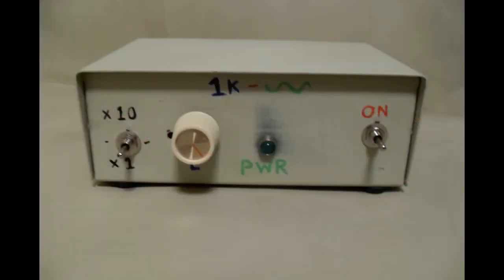Optionally, on mine, I added an LED. I have a volume pot. I put in a switch to toggle between the different volume levels, the 1 millivolt, 10, and 100. So I threw a toggle switch in there, and I didn't use the 1. I used the 10 and the 100. And then I've got the volume knob to fine-tune so I'm not blowing my doors off or too quiet. This circuit could run just fine off of a 9-volt battery, or in my case, I have a power supply here, so I went ahead and threw a DC input jack on it. I constructed it with strip board or Vero board, which I ordered, but you could also use a perf board for this project too.